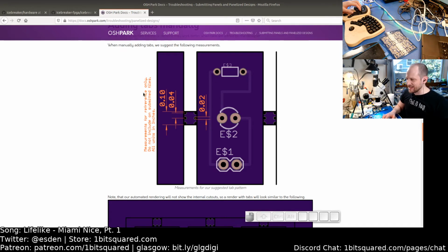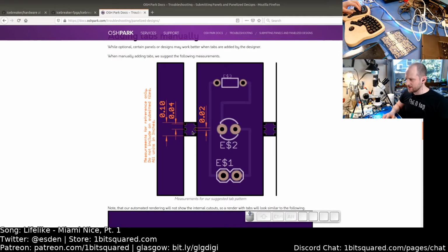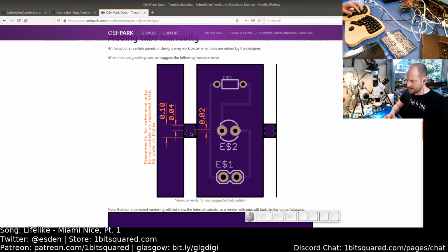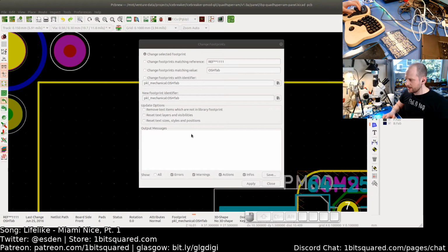So this is imperial measurements, and I converted it to metric and took a little bit closer measurements based on the metric system, because I design my boards mechanical and electric in metric as far as I can, and it's only broken by the imperial connectors, which are also 1.27 millimeters or 2.54 millimeters pitch, which is also doable in microns.